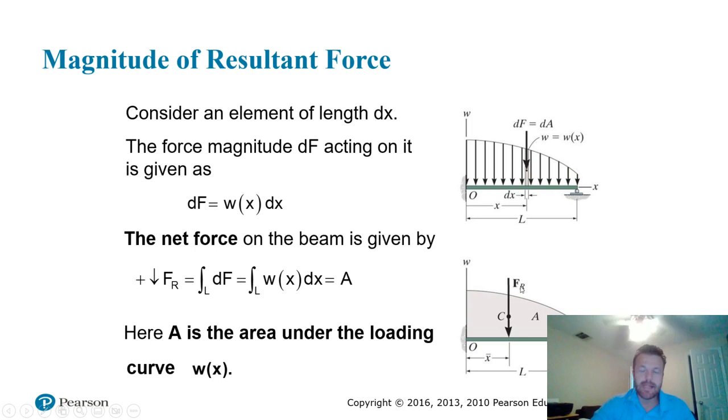The problem is, say the area under the curve turned out to be 40 newtons. What you're doing is you're replacing the distribution of the force by an equivalent magnitude. But in order to really model it as a single force, you have to know where to put it. So here, they've shown, well, what if you just put it at this distance x bar? And for those of you that have seen physics beforehand, you're probably familiar with the fact that the reason you put a bar over the x is it gets to the idea of the centroid, or some kind of geometric moment of this area.